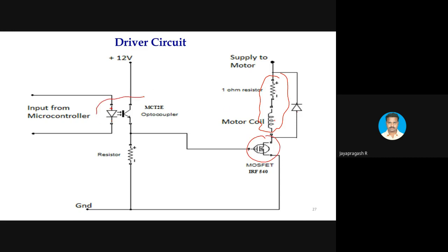For that, we use a driver. You know what a driver is, right? A driver is used to provide electrical isolation between the high power electronic circuit and the low power electronic circuit. The PWM signals are generated using a microcontroller. We use a PIC microcontroller and generate the PWM signal. A low power version microcontroller operates at 3.3 volts, and a regular microcontroller operates at 5 volts. If VCC itself is 3.3 volts, the control signal derived from the microcontroller also has a range of 3.3 volts, which is not sufficient to trigger the power device in a power electronic circuit. So it has to be amplified.